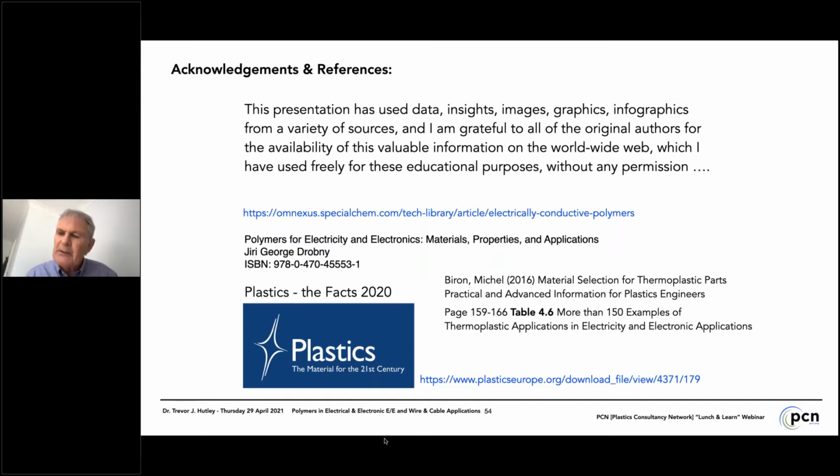So actually, I had a project on this many decades ago when I worked in Dunlop Central Research. We called it post-fabrication cross-linking. You use the advantage of thermoplastics for fast processing and ease of shaping and the economy of that, and then you combine that with post-fabrication cross-linking using electron beam, or peroxide, or moisture curing technologies, or gamma radiation, to cause the material to become thermoset and have higher thermal performance than would normally be the case. So that's how we think about thermoplastic and thermoset materials.